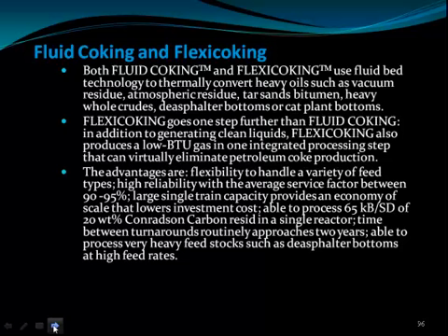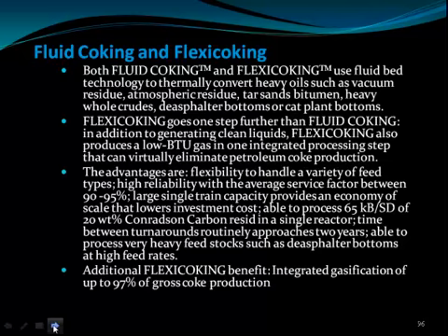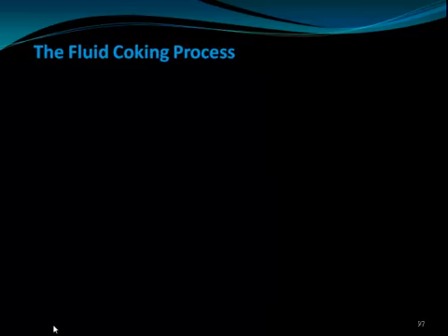Time between turnarounds certainly approaches 2 years. It is able to process very heavy feedstocks such as de-asphalter bottoms at high feed rates. An additional flexi coking benefit is integrated gasification of up to 97% of the coke.